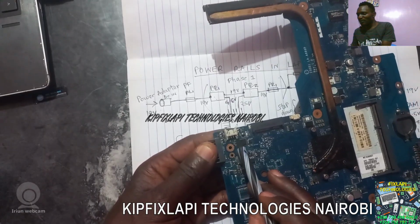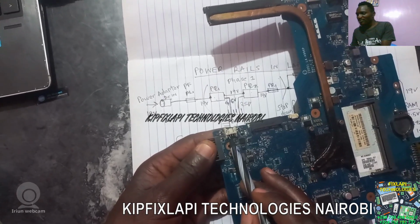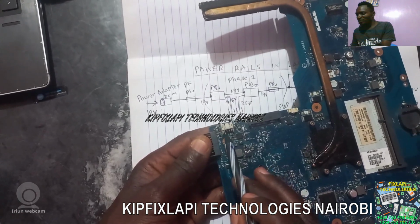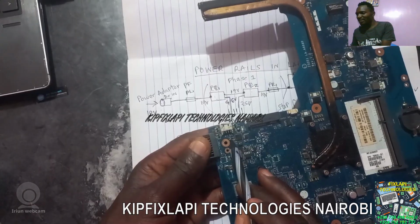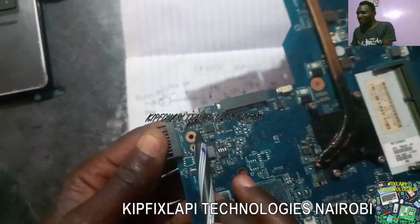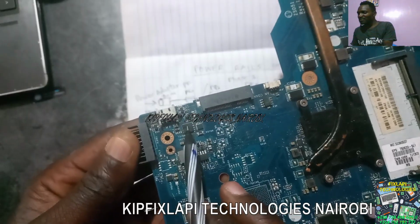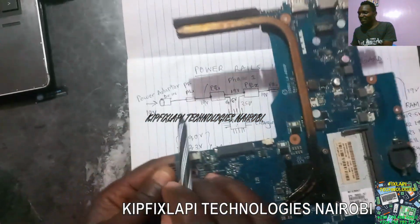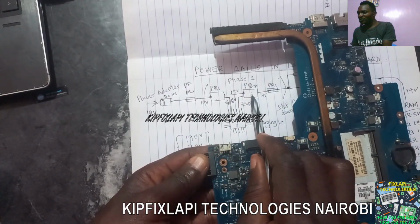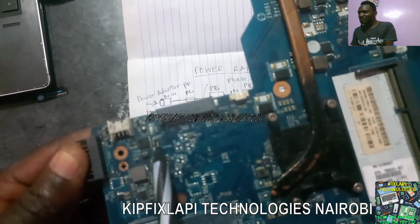So I hope you know how to test for the positive terminals for the port. Those positive terminals, if you test, you will find the continuity between the positive terminals and the power inductors. So these are the inductors. I don't know whether you can see them. Yes. This is MOSFET 1. As I said here, we have inductor, you have MOSFET 1, and then you have MOSFET 2. So this is MOSFET 1, this is MOSFET 2, right?